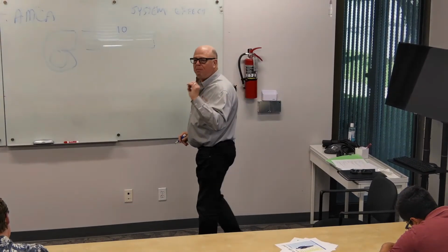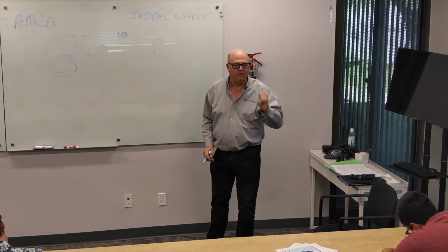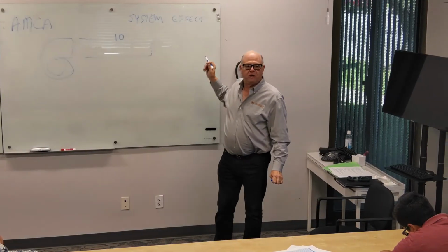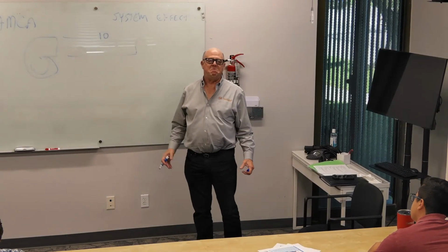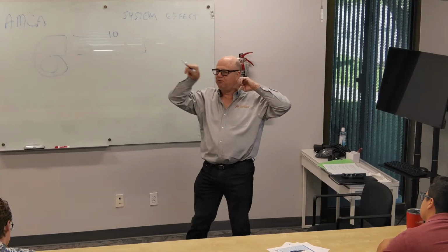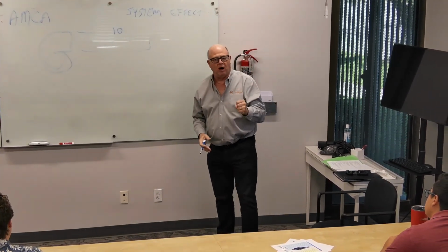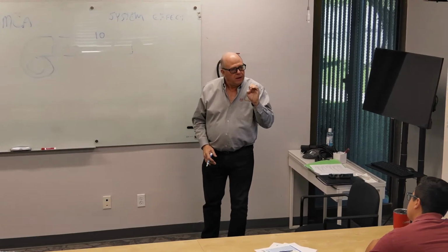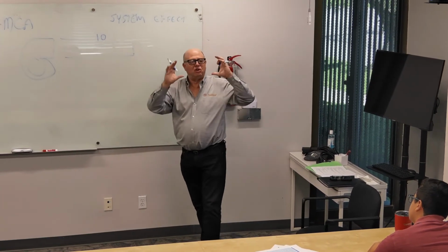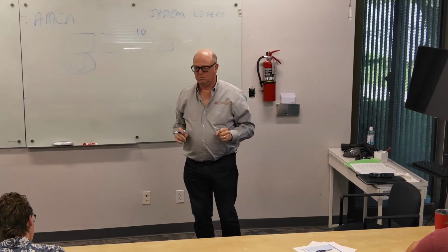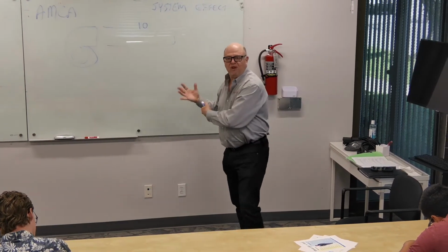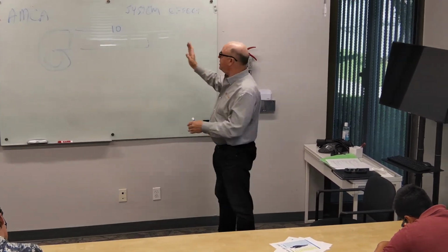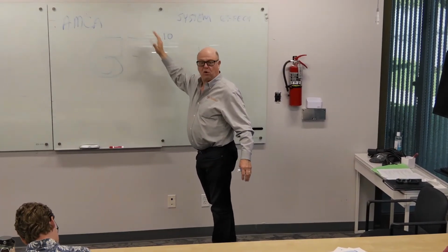How many real life projects do you ever design that have 10 straight duct diameters coming right off the discharge of the fan? It's pretty rare, isn't it? I mean, maybe you might have one up on a roof or something, but this doesn't happen very often. System effect is the correction factor, measured in static pressure, that you come up with to correct the fan curve, because the fan curve isn't right anymore if you're going to turn the duct over here.